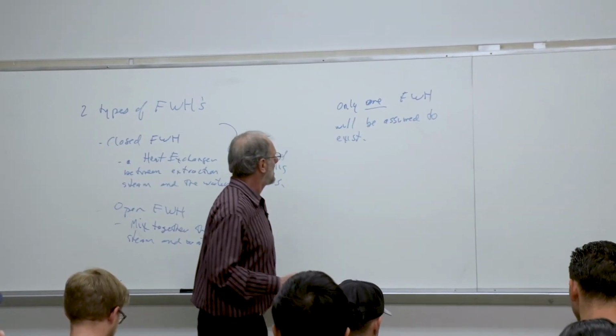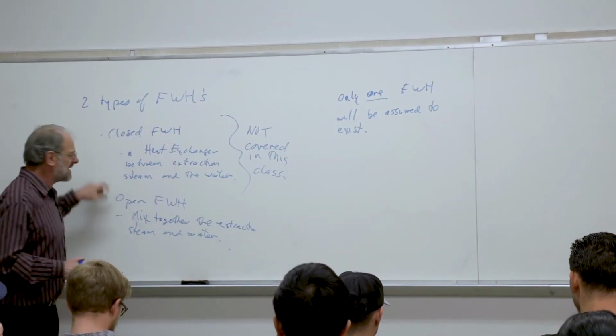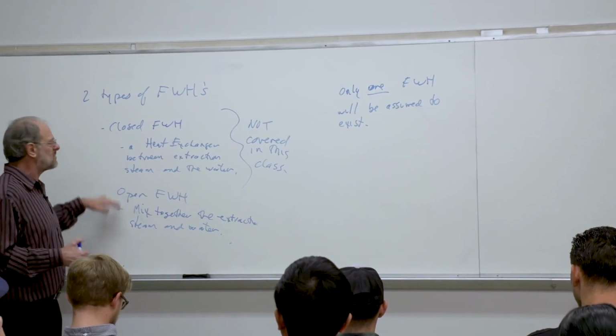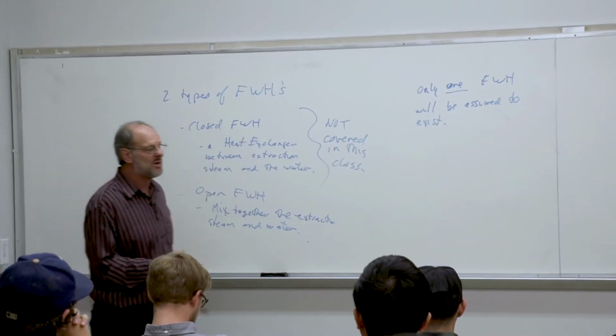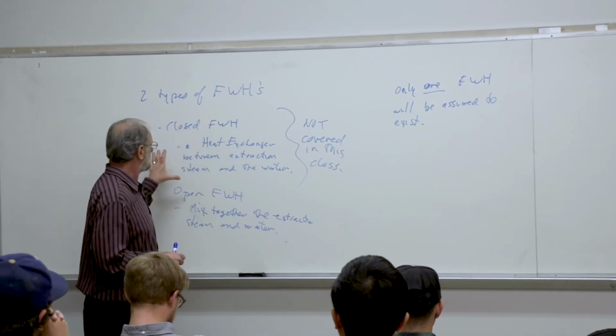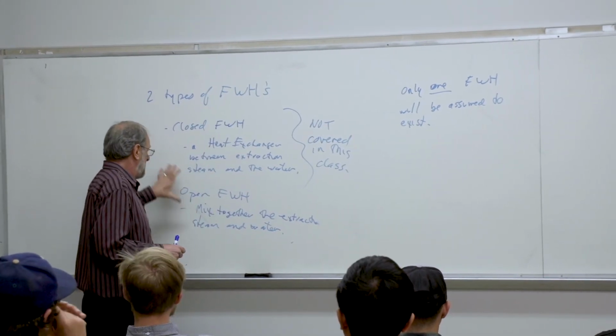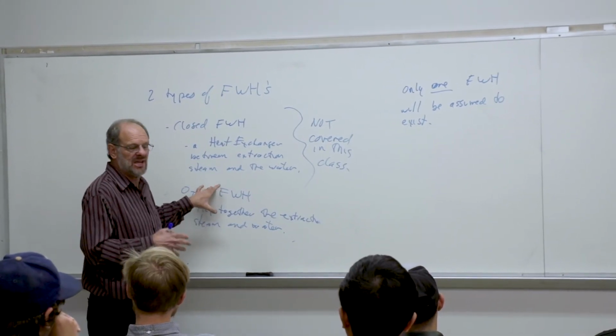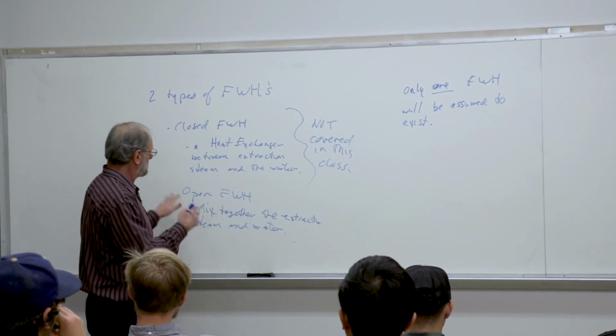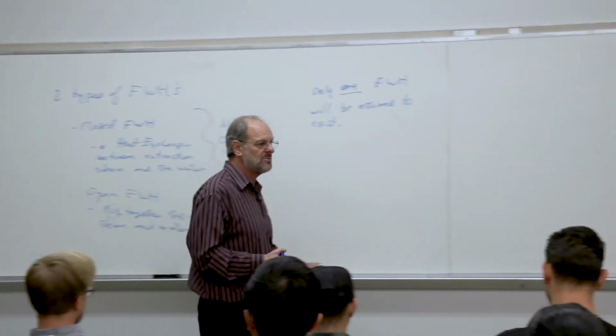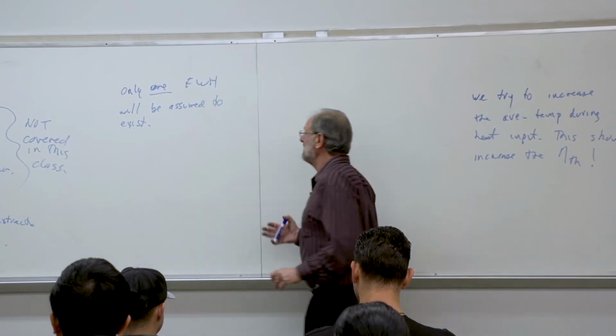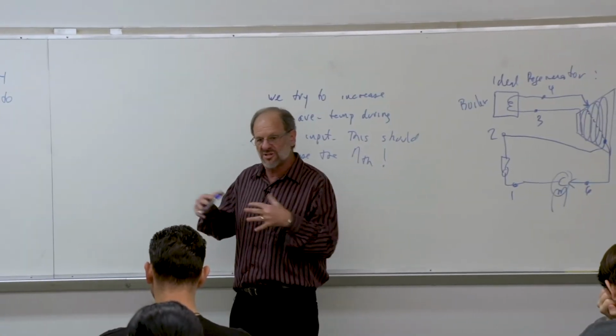It's important. Closed feed water heaters are actually cheaper than open feed water heaters, and that's why you find so many closed feed water heaters in existence. And as such, you really only need the open feed water heater, not even for feed water purposes, although it helps, but also, again, for deaeration purposes. Nonetheless, that's a side point. We're only interested in the thermodynamics.